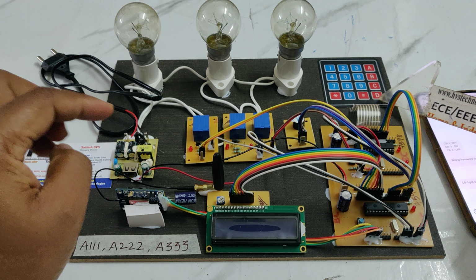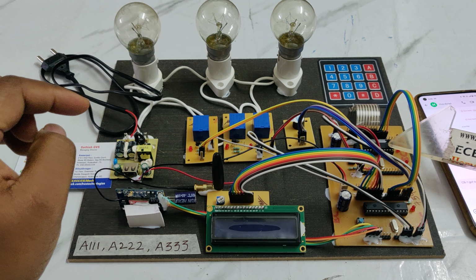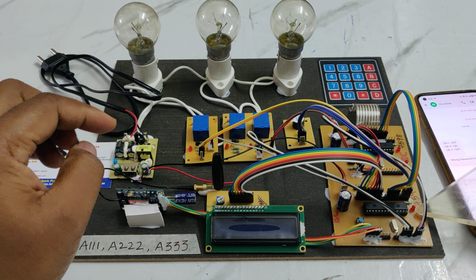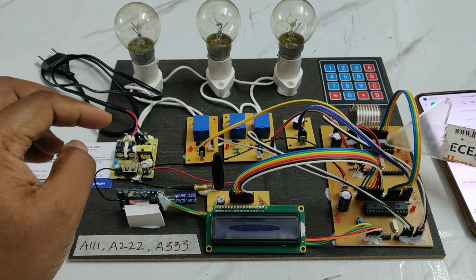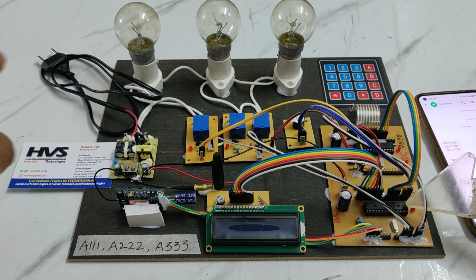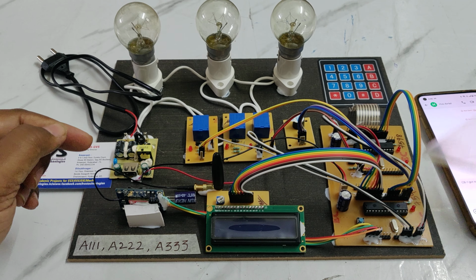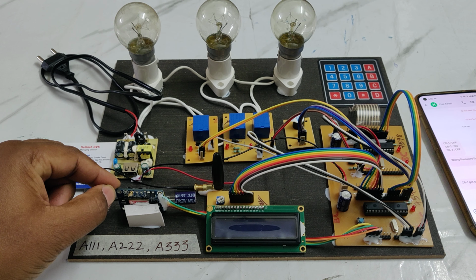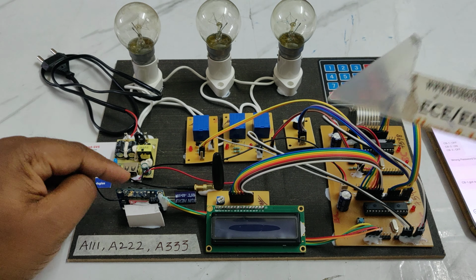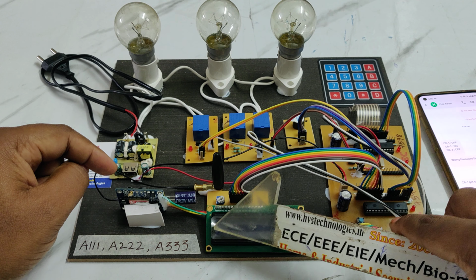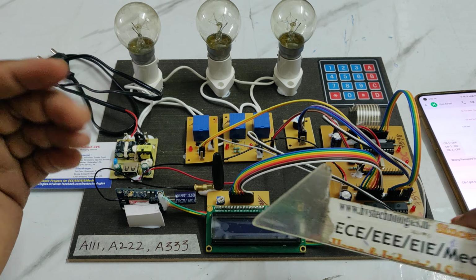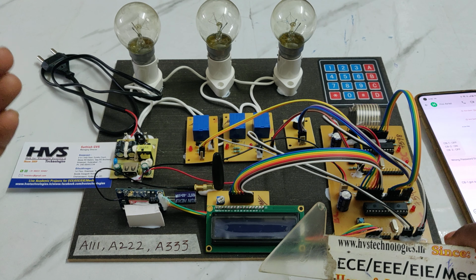For locally reading this keypad we are using this microcontroller, and this microcontroller for GSM. The keypad is input to this microcontroller. It will send the information to the microcontroller about what password got entered over here, and the GSM will read the messages which were sent to the SIM card and interface to this PIC microcontroller, and all the status is locally monitored on the 16x2 LCD screen about the message arrival or password authorized.